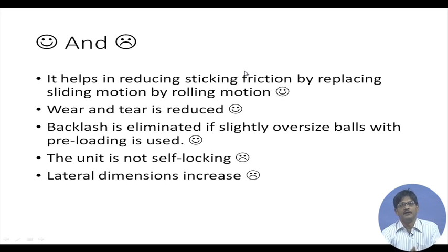When we are in a region just in between metal to metal contact and fluid film lubrication, in that region the motion of a member against another engineering part becomes uncertain. That means it might be sticking at some time with the other body, and it might be slipping against the other body at some time.